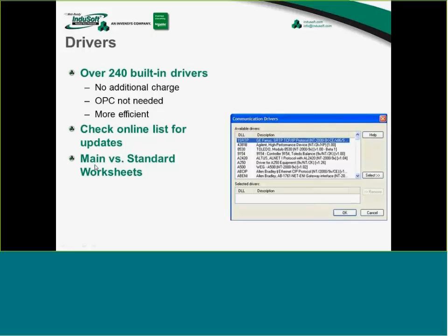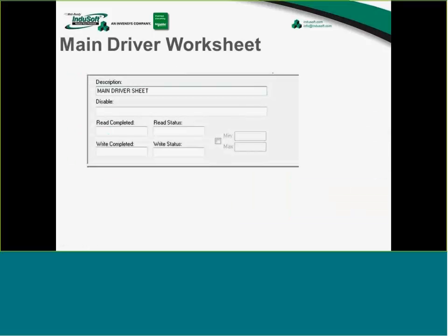And we'll talk a little bit about main versus standard driver worksheets. And I know Jay is going to cover a little bit of this in his presentation, but the main driver worksheet has a header, or the top part of this, that looks like this, and the bottom part is actually where you would tie the tag name into the PLC I/O address. And let me pull up a real one of these.